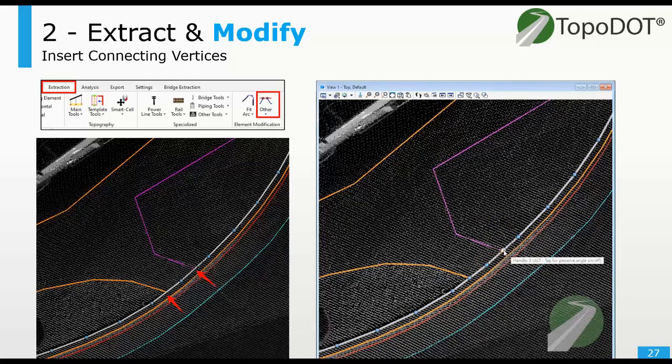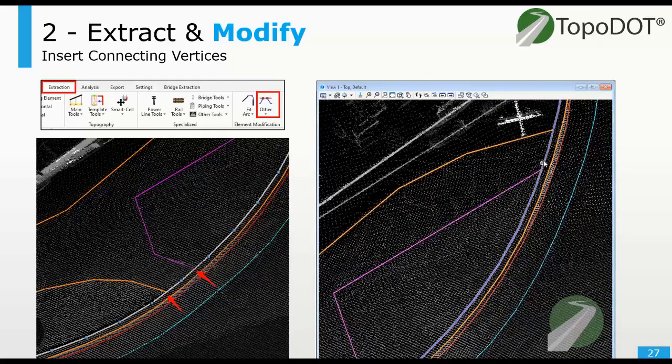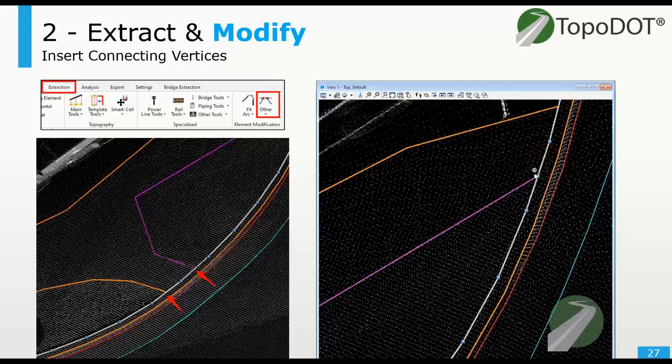But you also need to make sure that those nodes are created in case they were not touching. There is another tool called the Drape to Intersection tool that we didn't discuss because it's a little bit older, that you could also use to create nodes there and intersect those lines together if need be, if you don't think they're touching. So let us know if you want to learn more about that. It's also on the wiki, and that's called the drape to intersection.